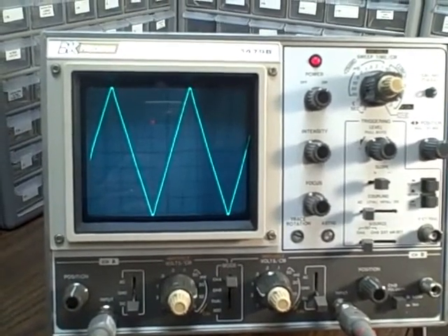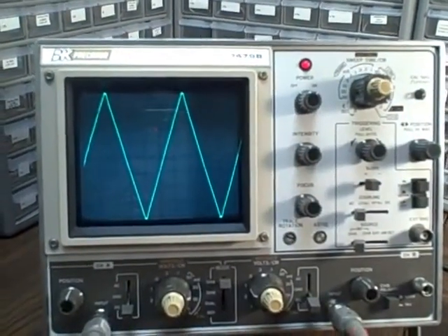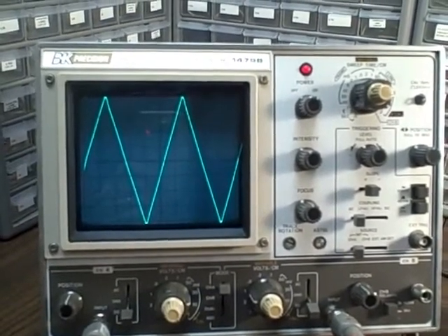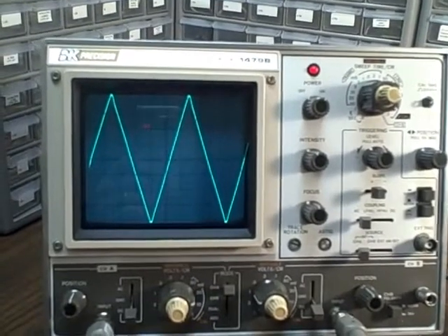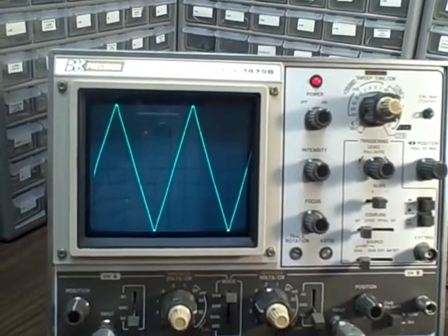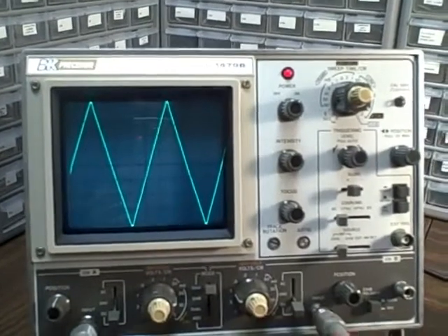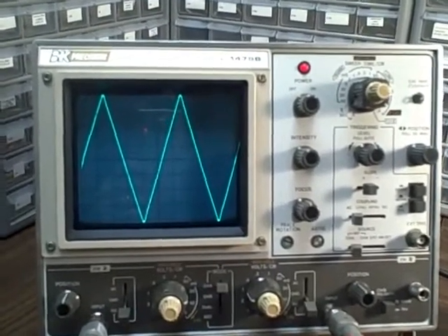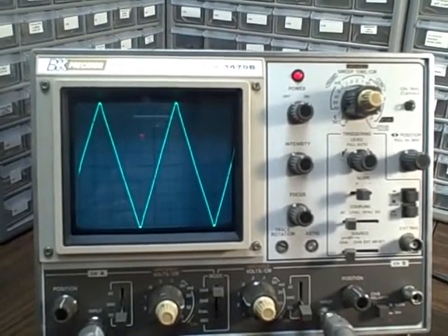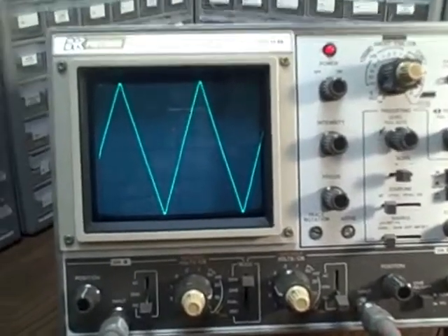We also should have observed during that entire period that we had a triangle wave being demonstrated. So we have linearity and we are faithfully reproducing our signal. We're reproducing our voltages properly, our signal linearity, and we are doing it within the proper time base. So this is a good scope. The only thing left for me to do now would be to try and measure our bandwidth, and we'll handle that in a minute.